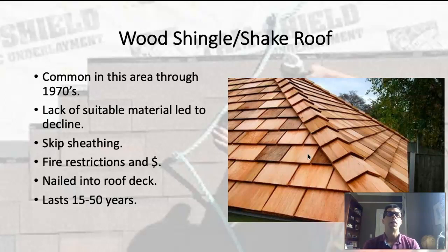And it also had the benefit of drying out the backs of the shingles. So that's another thing that contributed to the extended life of the shingles. Okay, it was a piece of wood on a roof. It got wet. It soaked up a bunch of moisture. But with that skip sheathing, the backs of the shingles were exposed, and so there was lots of air blowing against the backs of those shingles, and it contributed to the drying potential of those shingles.